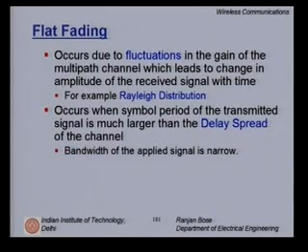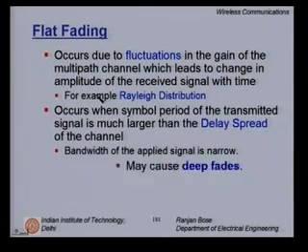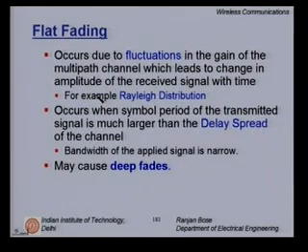The bandwidth of the applied signal is narrow as compared to the coherence bandwidth of the channel. We are talking about the flat fading scenario. Flat fading may cause deep fades, out of which we have to come out using some other technique like time diversity or antenna diversity.